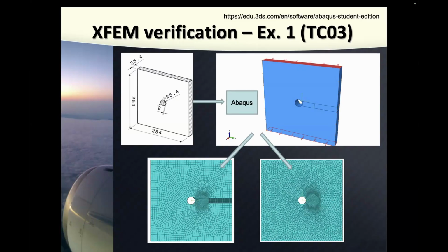In order to compare the results. Because one of the most important things, I believe you know that in finite element analysis, is the quality of the mesh. So what is the number of nodes, what shape of the element, what kind of element you're going to use, and so on. So it looks easy, but in fact, it takes a lot of time.